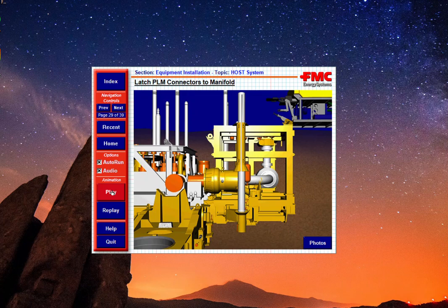This is the connector, and it works the same on the Christmas tree, connecting to the manifold ends. It has the same type of connector. All of them are more or less the same. And if it's more than 1 degree inclination, it doesn't mate up, and the whole well is very nice, but it cannot produce. The connectors are then hydraulically locked to the manifold hubs.